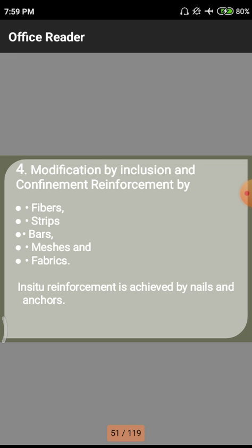The first one is the fiber. Fiber means an extra additive which is added to the particular material to strengthen the bond between different layers and different particles. Normally in cement materials we use different kinds of fibers like steel fibers, glass fibers, crimped fibers, polypropylene fibers, and other plastic fibers and synthetic materials to strengthen the concrete.